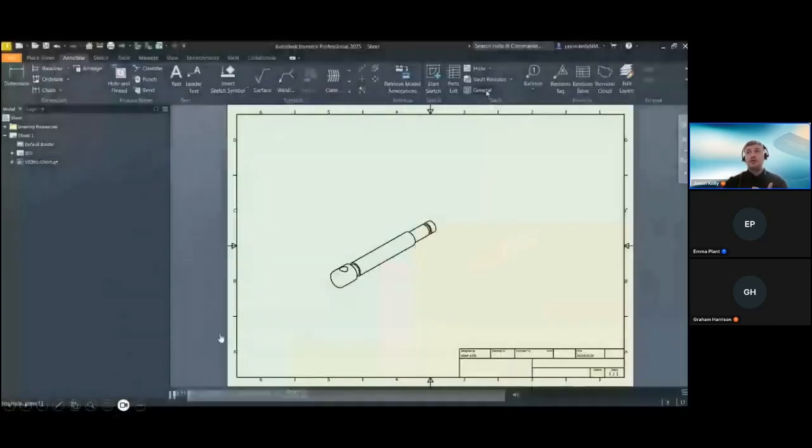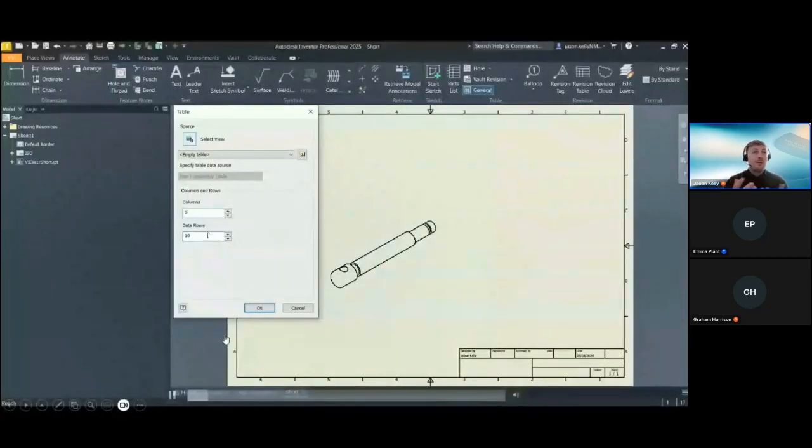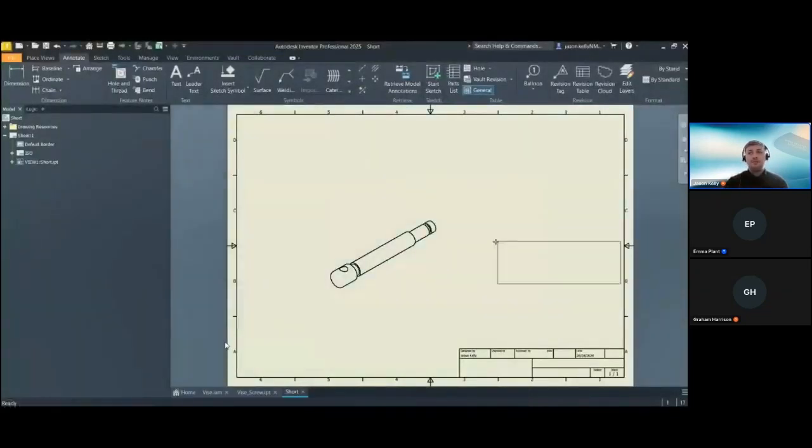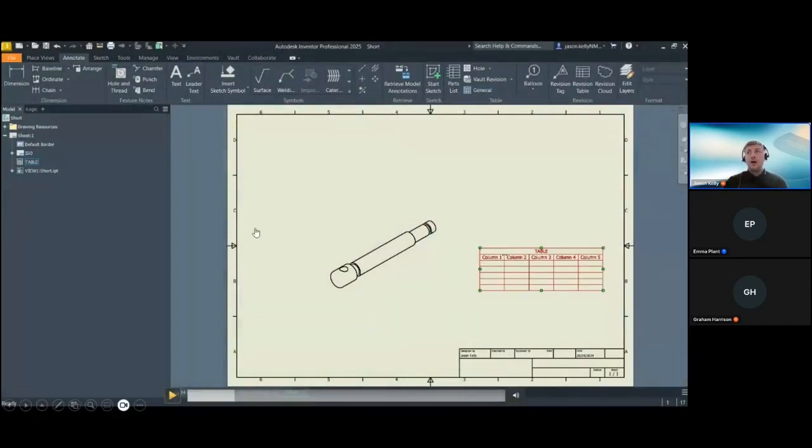It's going to merge your cells together to allow you to format your table in a more appropriate way. Just to start out, this only works in your general table command. It doesn't work within your parts list at the minute. It doesn't work anywhere else. It has to be a general table that doesn't have a reference to an Excel spreadsheet. So it has to just be in your general table enhancements within there.